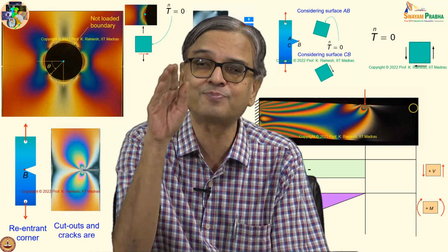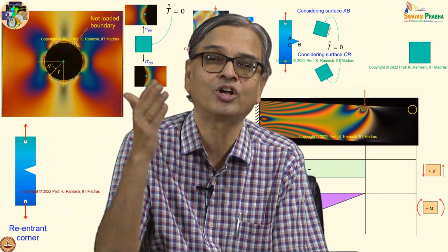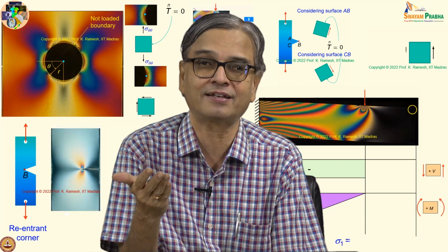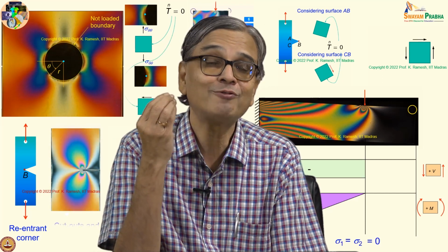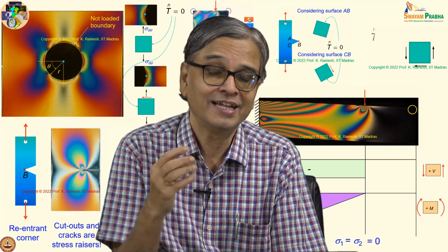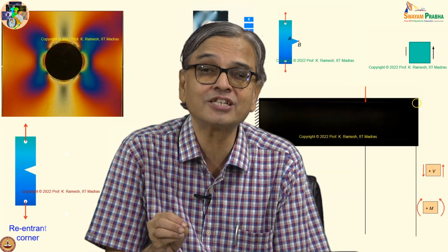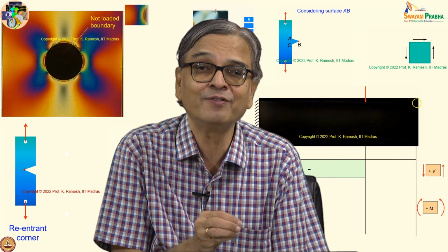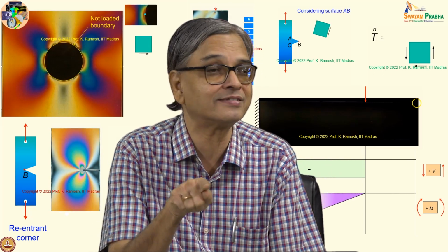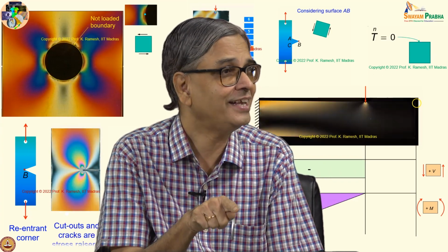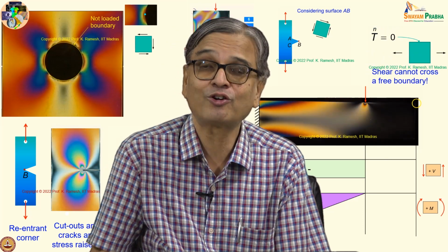Now you have a very small window which is also curved. So any opening that you have, either in your buildings or your aircraft, which is a pressure vessel, you have to design those openings properly. And this is a very nice example. If you simply say maximum shear stress theory and then investigate the failure, you can burn your fingers. Fine. So you have to be very cautious.